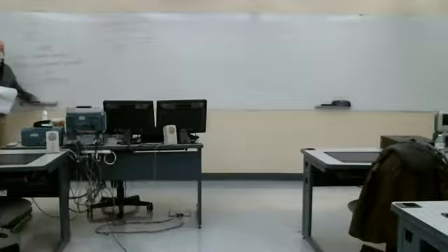At the peaks, which would correspond to when B and rho are at 90 degrees, or when there's maximum flux through the loop, the rate of change of flux is 0. So a little bit surprising, maybe not, depending on how comfortable you are with Faraday's law, that we actually get a 0 voltage when there's maximum flux through our loop, and we get maximum voltage when there's 0 flux through our loop. But again, it's the rate of change of flux that generates the voltage.